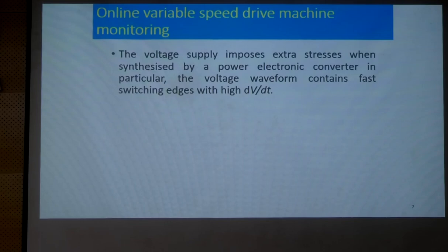Also, in the standards, partial discharge inception voltages for low voltage machines are given. Even endurance tests are to be conducted for medium voltage range machines also. Such standards are imposed so that the machine will work effectively and continually for a long time, with proper functioning throughout its life.